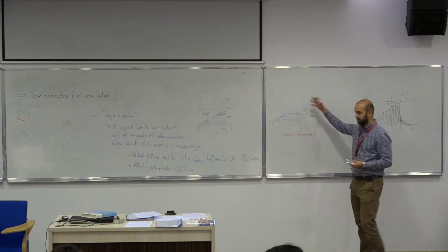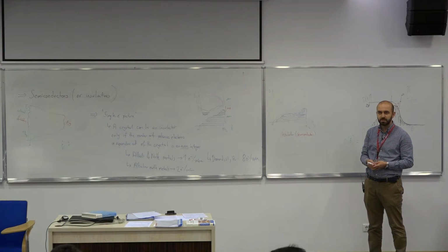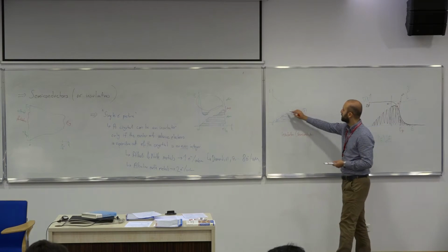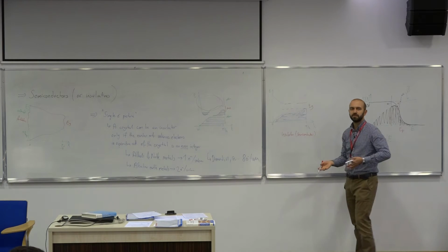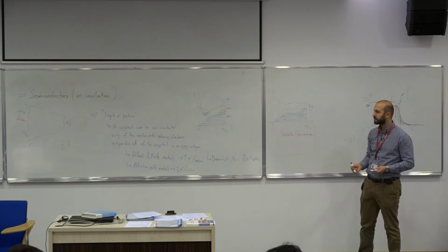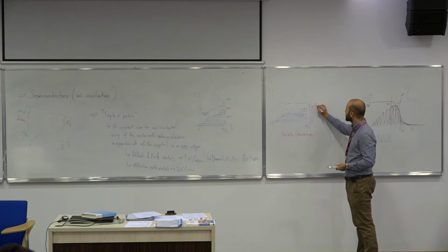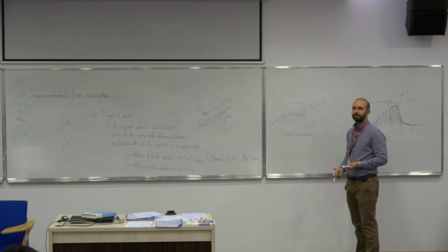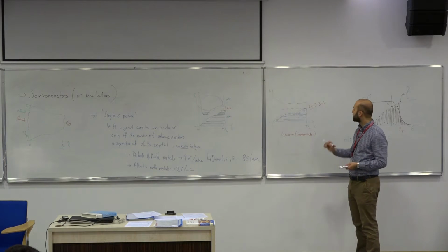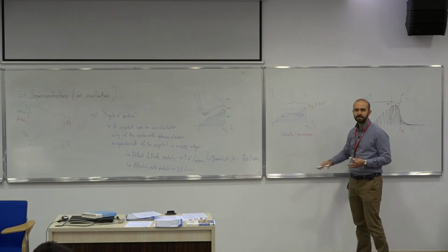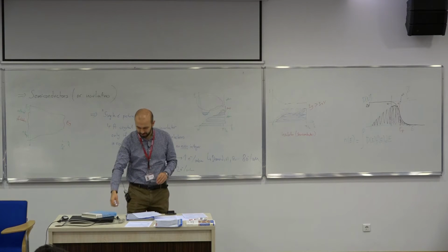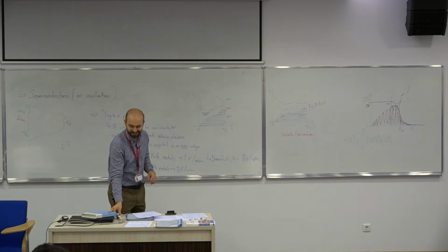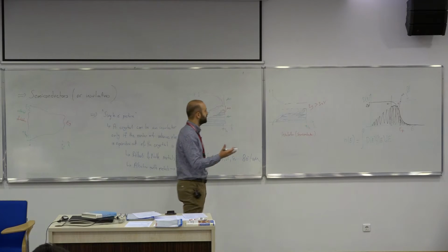What determines it being a semiconductor or insulator? The size of the gap, yes. So the size of this E_G determines whether we call it an insulator or a semiconductor. Typically, if this gap is greater than 3 electron volts, you can say that it's an insulator. If it is less than 3 electron volts, you can say that it's a semiconductor. But that definition can be altered with respect to the hype that you want to create.